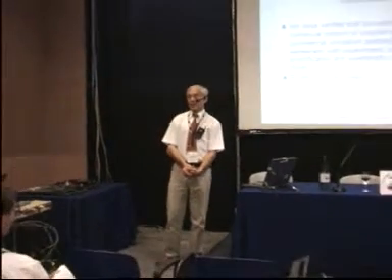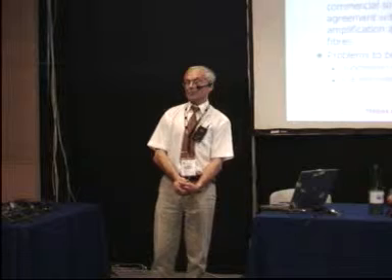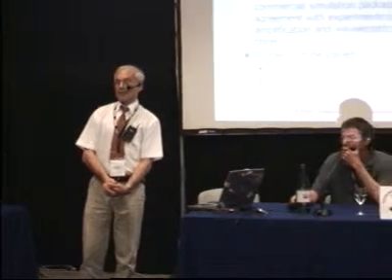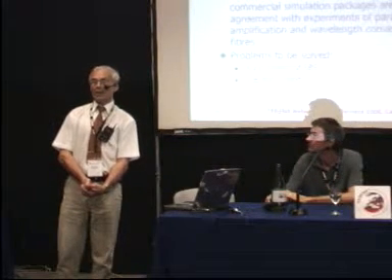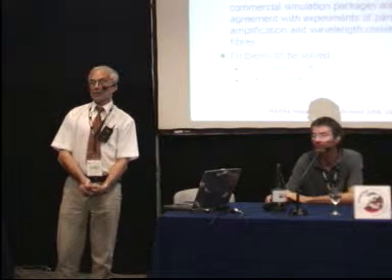Unfortunately, not having the demultiplexer for the idler side, we were unable to do that for the generated idlers. So it will be easy to measure the signal-to-noise ratio, but we did not do that. But the proof for the usability of these newly generated signals was just to send them over 80 kilometers of standard single mode fiber. At that length you don't need any dispersion compensation because the Cisco platform can survive the chromatic dispersion of 80 kilometers of fiber without any dispersion compensation, so it was still operating.